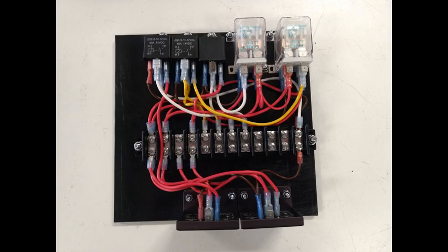Well, a logical question would be, why use a relay? Well, a relay can be used as a remote switch or to isolate circuits. You can use a low voltage, low current circuit to switch a high voltage, high current circuit. Or you could use a DC circuit to switch an AC circuit. And there's many uses for a relay.